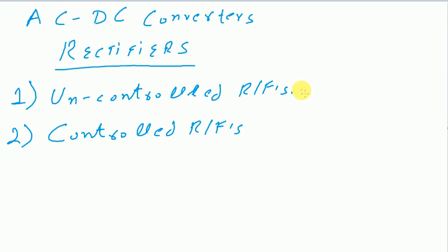So the same is the case here. The rectifier or converter circuits in which we employ a diode as a switching device are termed as uncontrolled, because as we are now familiar, a diode cannot turn itself on and off under the influence of any external signal, but can only be turned on and off by the polarity of the voltage that is applied across it.